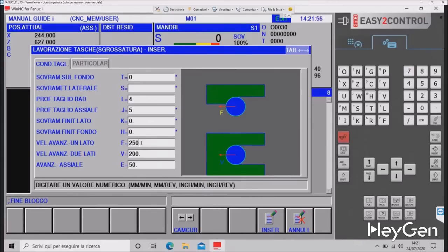It automatically sets it the same for me. And you see, I made a mistake. It's not adjustable. So the actual feed rate remains the same. This is a small limitation of the manual guide. Obviously with ISO, we wouldn't have this problem. Now, regarding the entry feed rate when the cutter enters from solid, the manual guide allows me to modify that. It's obviously more important because when I enter from solid, I need to lower the parameters a bit.